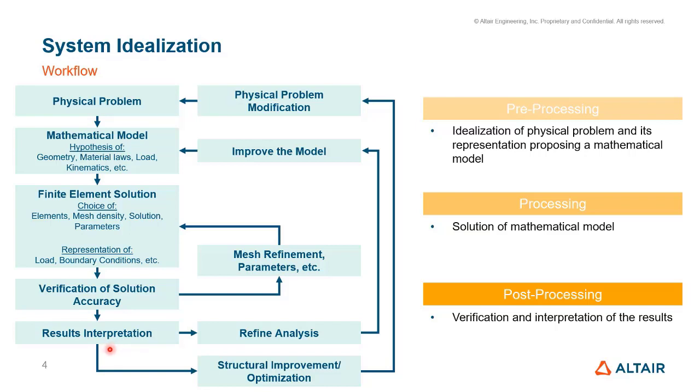So that's it that I wanted to show you in this presentation, covering really the fundamental process about finite element method, how to define a problem, how to create the mathematical model out of it, and calculate using finite element method, and also showing how it is the workflow inside SimLab, how can we create the mesh, apply the material, define the solution, set up all that solution, adding loads and constraints, and verifying the result and interpreting that result.